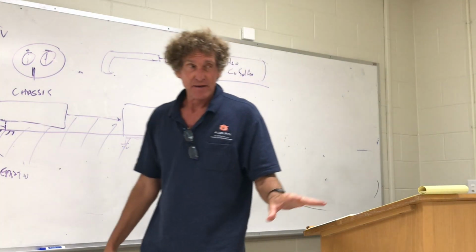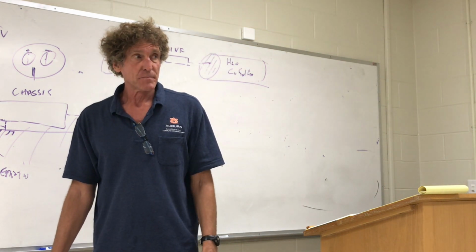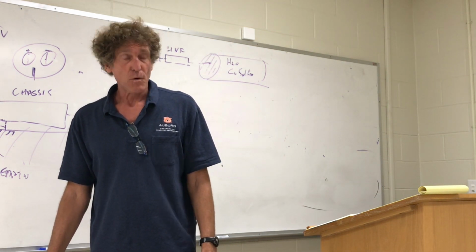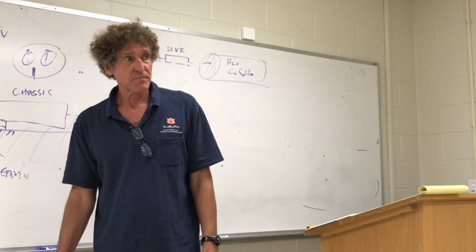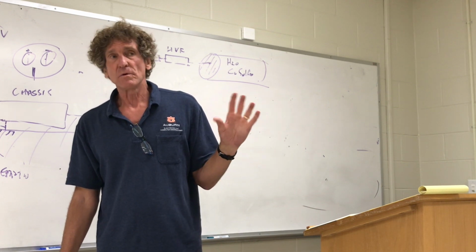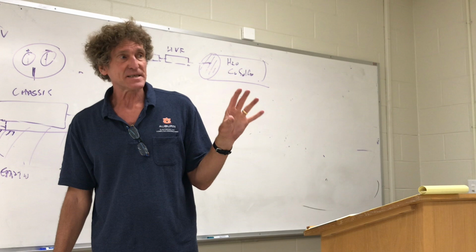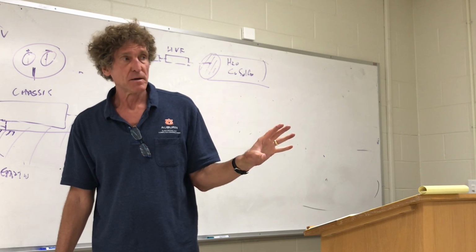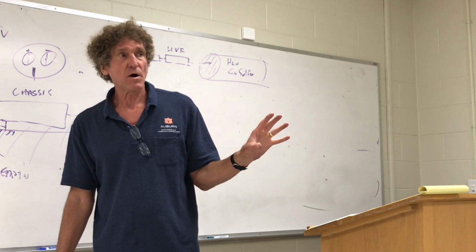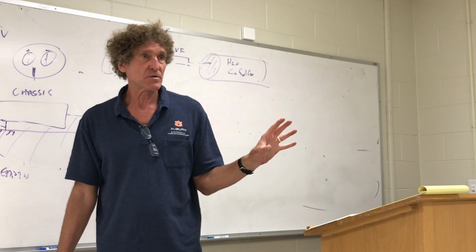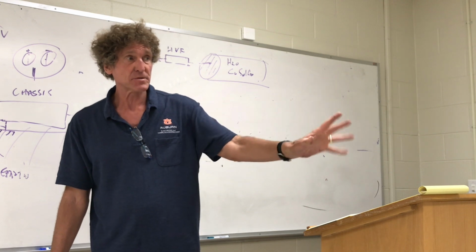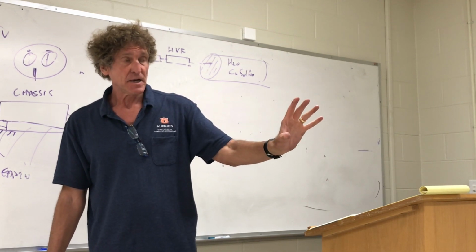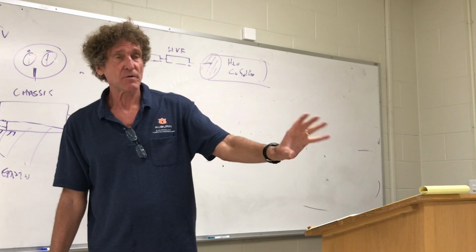So would you need something like this for a saltwater pool or something? Also, for grounds? Yeah, indoor or outdoor? Outdoor. Depends on the size. What kind of size? I was just assuming like any place, like at the beach or something where there's a lot of salt on the ground. Whoa, hold on. A pool that has electrical outlets inside the pool, I mean around the pool. Yeah, but anything that is near water, it doesn't matter if it's fresh or salt. If it's an AC electrical ground from Alabama Power, power coming in like that, it has to have a ground fault breaker.